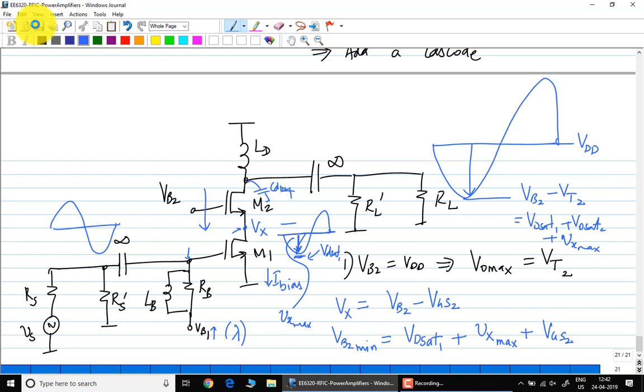Right? That's obvious. You have tried changing RL, but there are limits. Increasing VDD also has technological limits, because you break down the device much faster. Now, if you need watts of power, you can clearly not do it with this, because the CMOS device breaks down at a couple of 2-3 volts, 4 volts at the drain. The drain VDD is supposed to be like 1.5 volts, 2 volts, and so on.